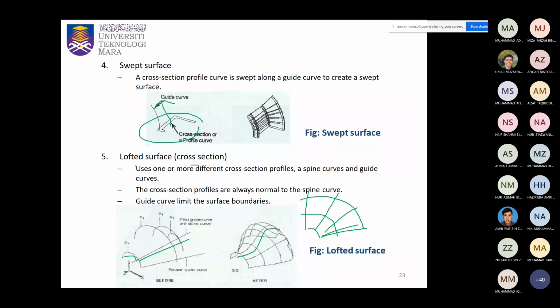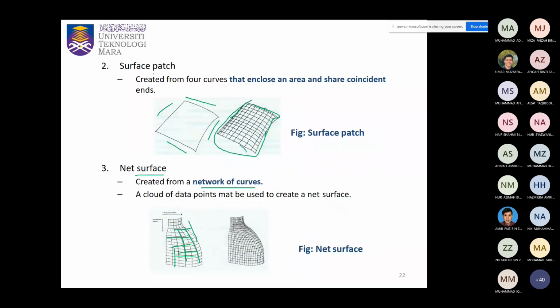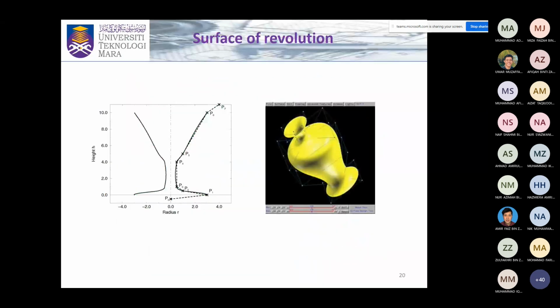So the concept of loft, right? What is different is you are able to, in one go, mix different cross sections and blend them to build a solid. Like for instance, this is done through revolve, where you are drawing the profile and then revolving it. So you could also use a multi-section solid where you have one section here, one section here, one section here, and then blend them with a guide curve.